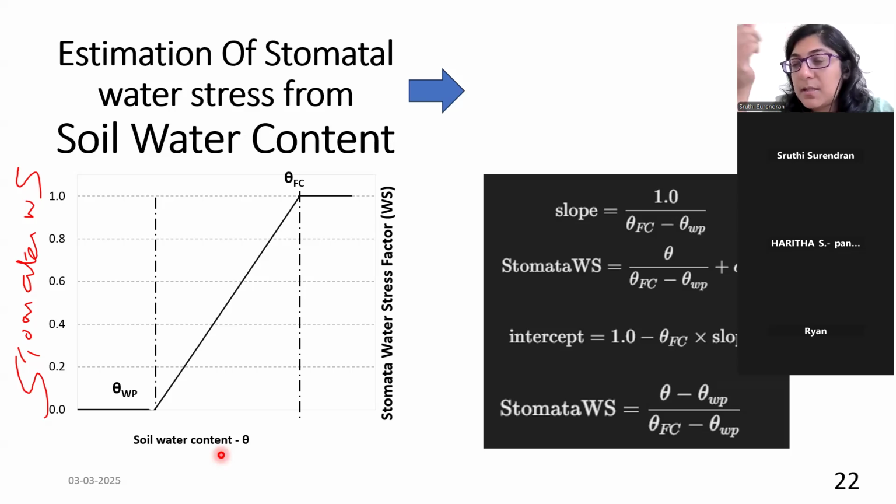All of this helps in estimating the soil water content based on the amount of sand, silt, clay, organic matter, etc. Say when you take a volume of soil, 21 percent of the soil is sand, then we have 60 percent clay, and the remaining percentage is silt. Based on all of these percentages, we can find out the soil volumetric water content.